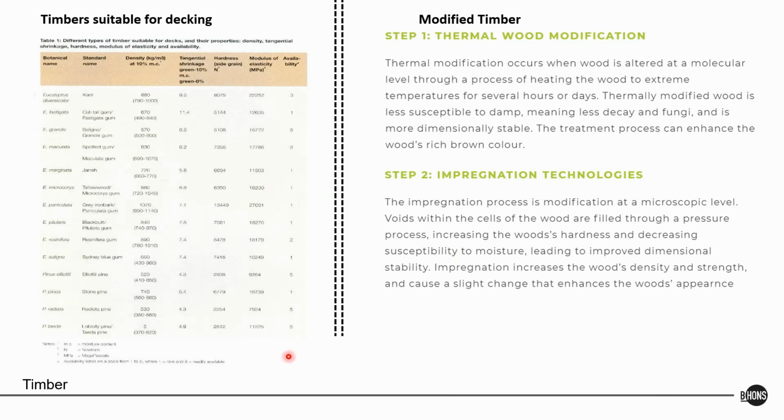You can look into other timbers such as balau or Rhodesian teak, which is a hardy hardwood, often tropical, coming from more tropical forests, and those are very nice timbers to use because they often have an insect repellent in the wood already, so insects don't like it, and they're very hard, so the sun and dry conditions don't damage them. So often you can, like balau, simply just use it. You don't even need to treat it. But be careful. Those often come from endangered woods and so forth. So there's an implication of using hardwood.